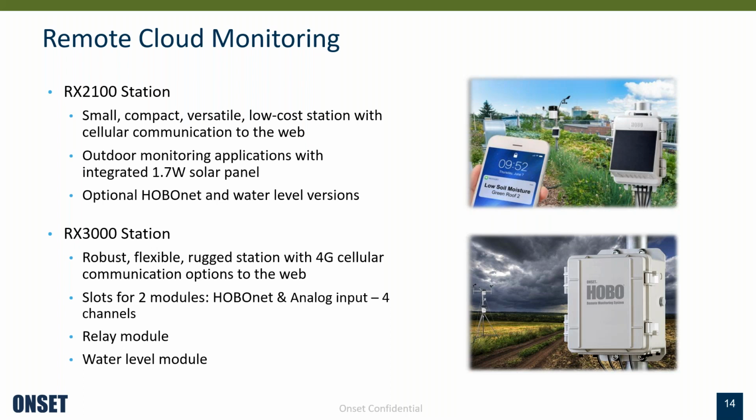What's pictured on the top is that what looks like that black square is a solar panel. So this has memory, its power and batteries. It's powered by that built-in solar panel. You can plug in 5 sensors and you can add wireless sensors to this. A 1.7 watt solar panel is what is built in. If you're in an area that's shadier, you can add an additional solar panel, a 5 watt or a 15 watt, and that will override the built-in panel.